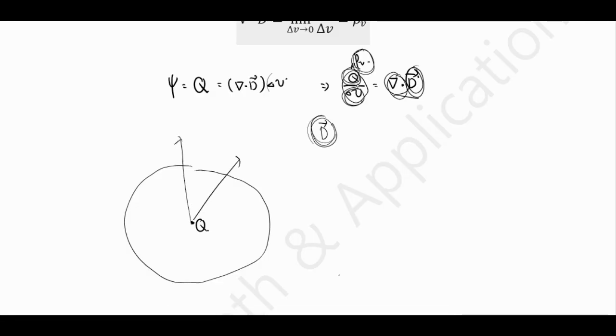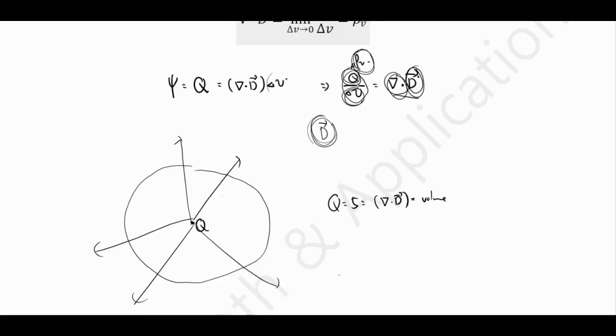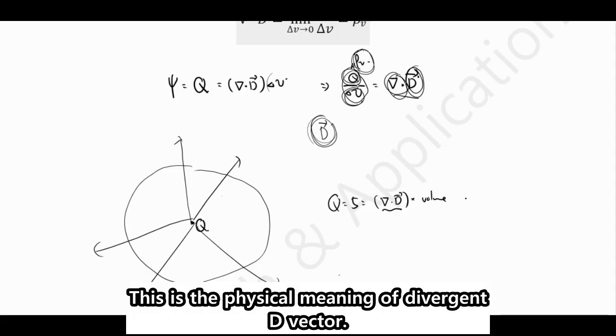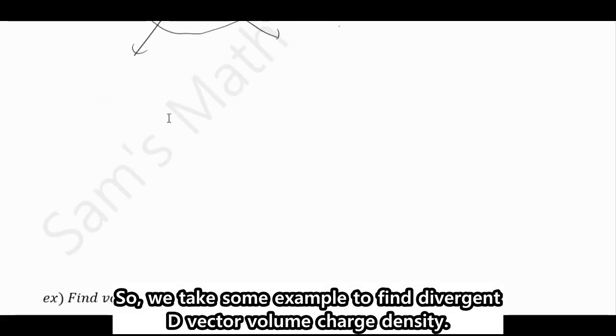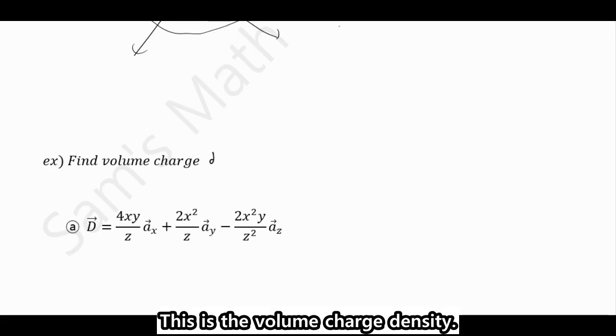This flux is the divergence of D vector multiplied by the volume. So the divergence of D vector is the electric flux quantity per unit volume. This is the physical meaning of the divergence of D vector. So we took some examples to find the divergence of D vector, which is the volume charge density.